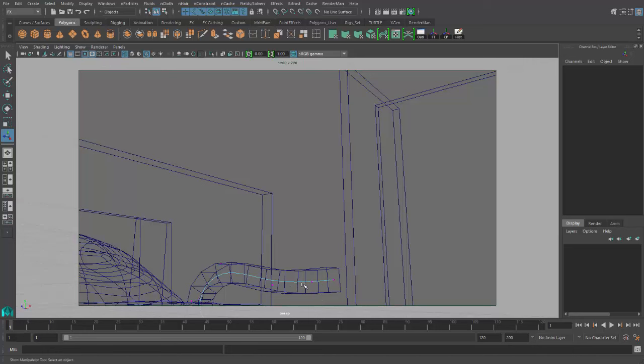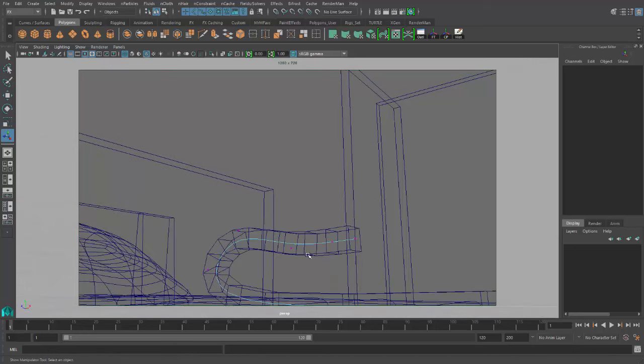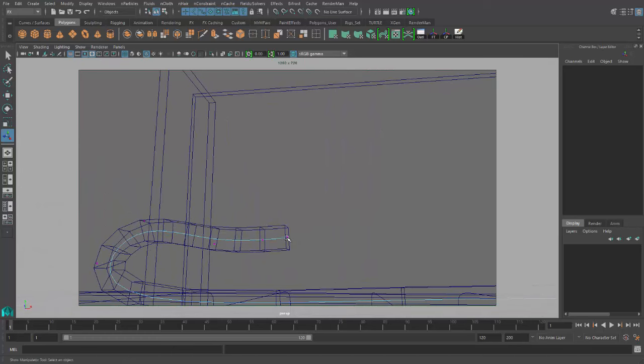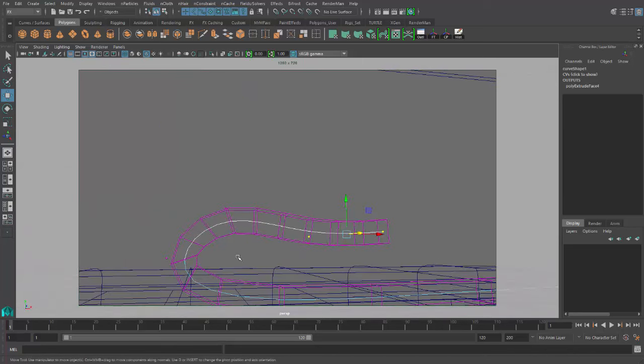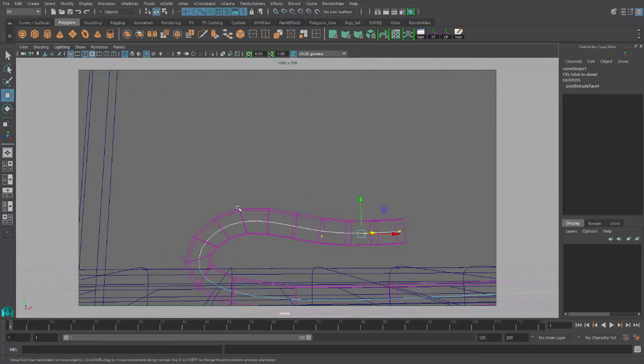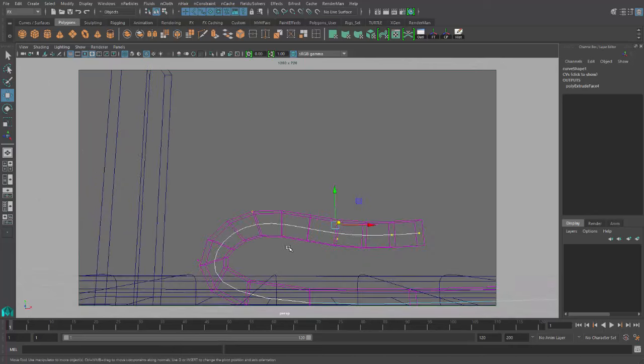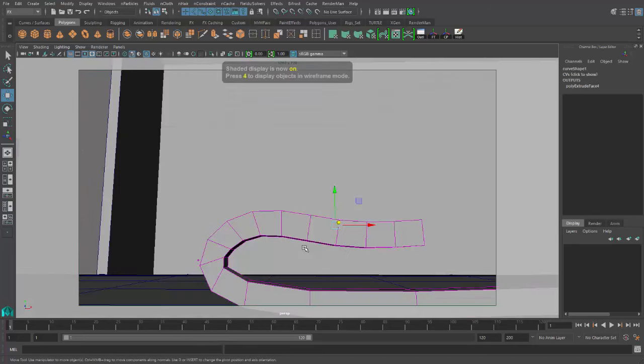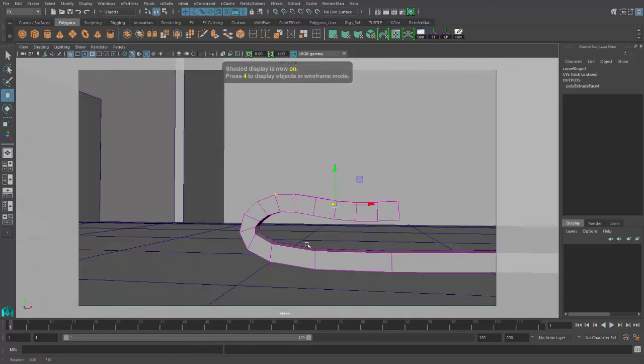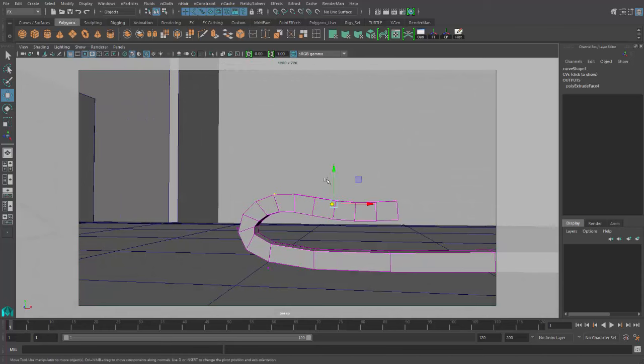Okay, it's in these little tiny pink dots, right? So what I'll do is I can select this dot. Press shift, select this particular dot here, over here as well. Okay, I think there's one here. There you go. Now let me press 5 to go back to the shaded mode. Now, with the curve control vertices selected, I can push them down.